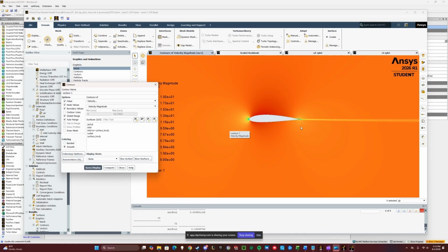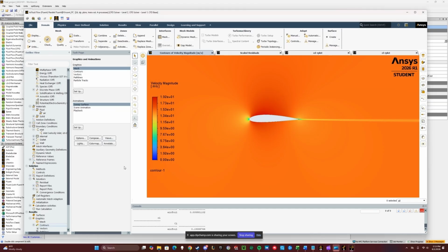So that's all good. So the next thing we have to do is click close. And now we need to see how we switch it up for each angle of attack. So to adjust the system for, let's say, 10 degrees angle of attack, I'll only be doing this once because doing it all 9 times or 10 is a little overwhelming. So we're just going to change it to a 10-degree angle of attack.